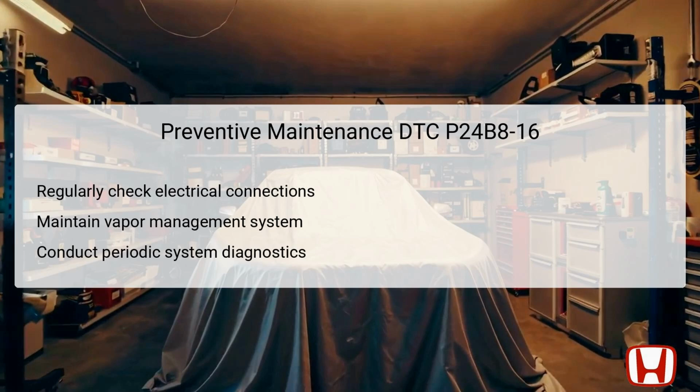Additionally, keeping the vapor management system clean and functional helps in mitigating issues with the pressure sensor circuit. Conducting periodic diagnostics checks using the Honda Diagnostic System, HDS, aids in early detection of emerging faults. By committing to these maintenance strategies, vehicle owners can protect against unexpected failures and sustain optimal vehicle performance.